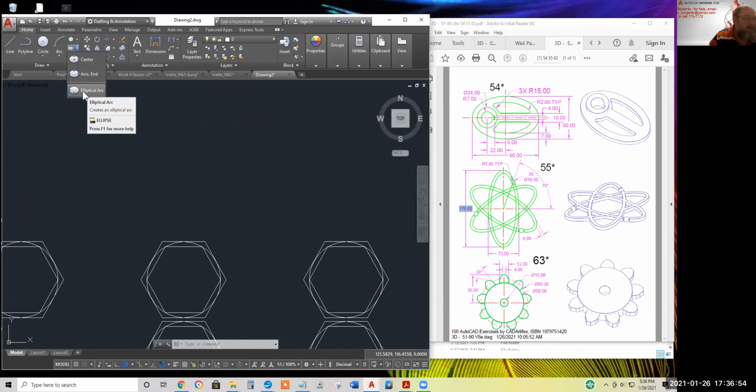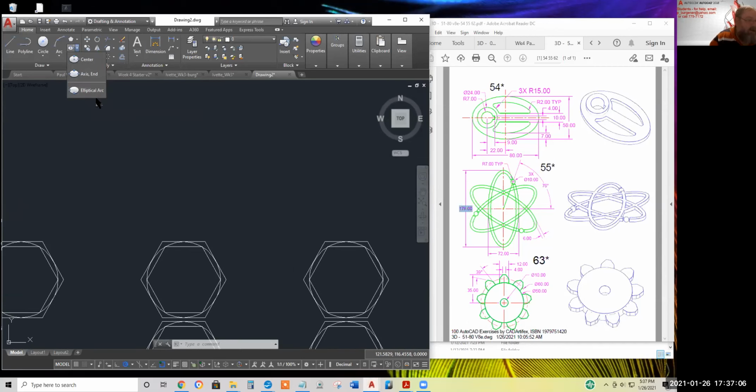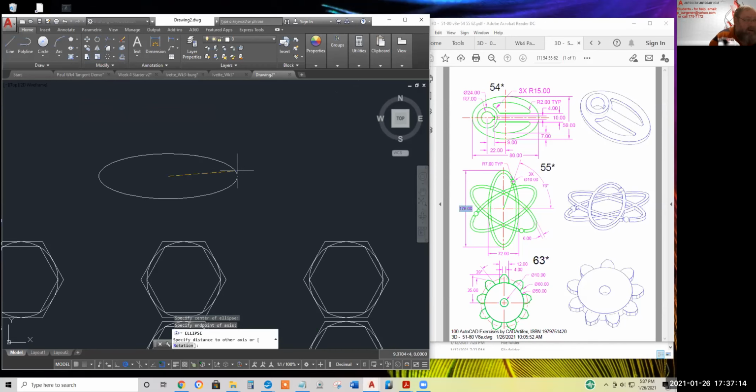I think one of these is nice for isometric drawings, but I got little use for isometric since 3D's not much more work and is far more useful. Anyway, I'll just demonstrate the first one. Click on the first one, pick a center point, pick an axis, and pick a second. Anyway, there's your ellipse.